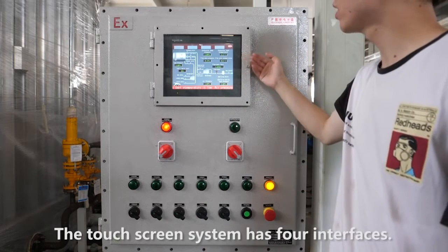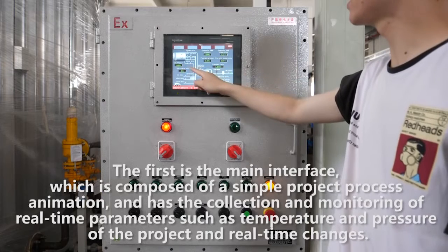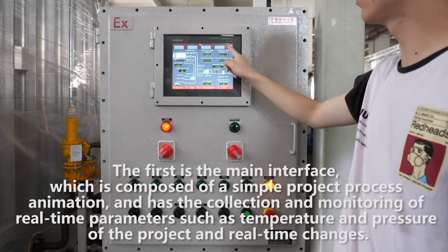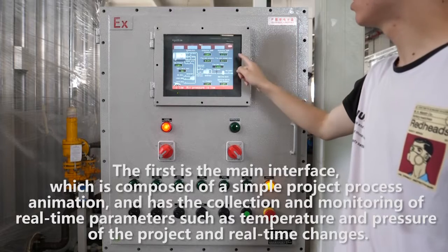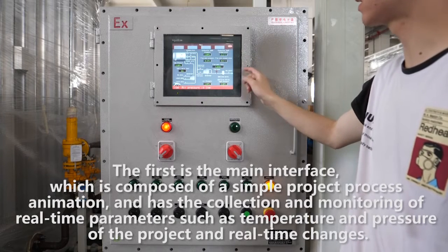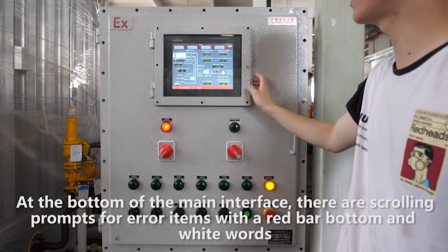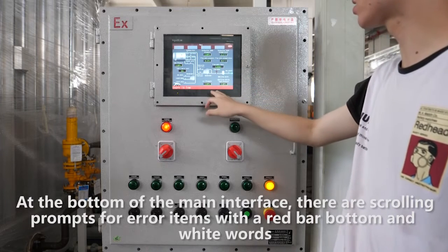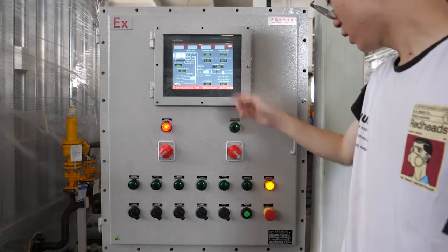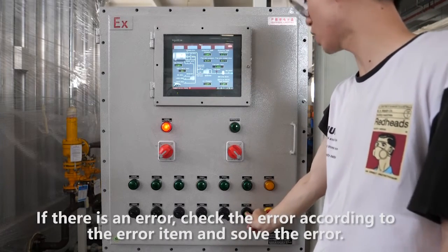The touch screen system has 4 interfaces. The first is the main interface, which is composed of a simple project process animation, and has the collection and monitoring of real-time parameters such as temperature and pressure of the project and real-time changes. At the bottom of the main interface, there are scrolling prompts for error items with a red bar bottom and white words. If there is an error, check the error according to the error item and solve the error.